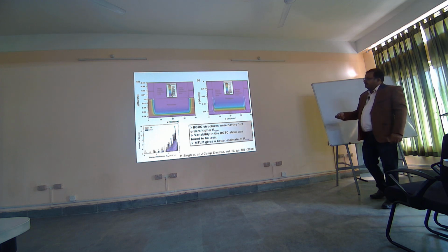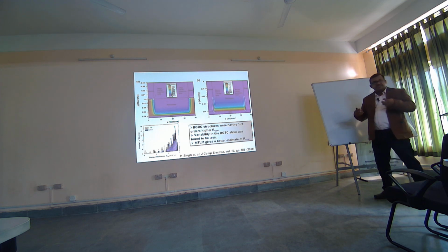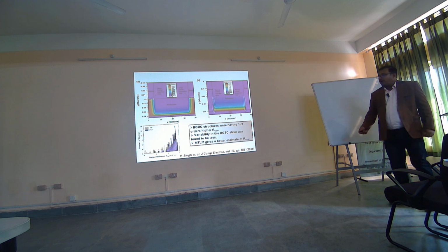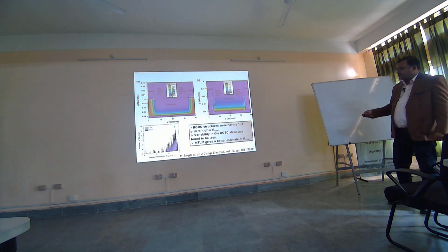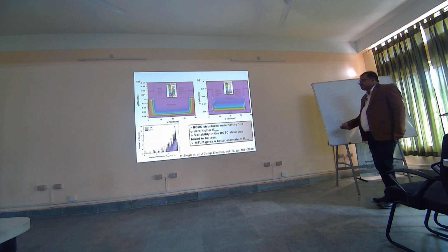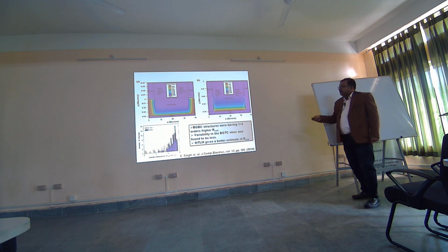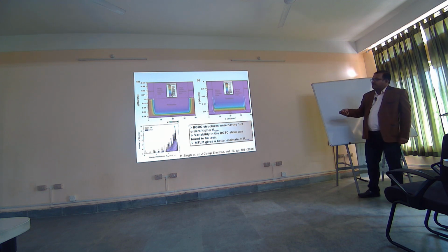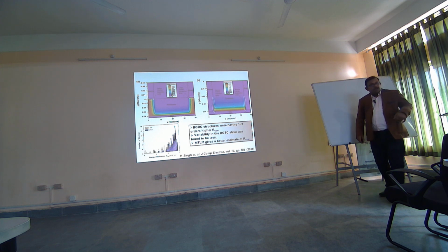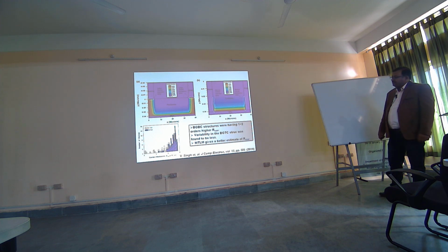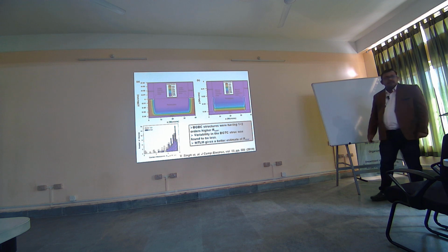Because of that, the contact resistance is also dependent on the interfacial area through which injection is happening. So we found that it is mainly because of the large interfacial area that the top contact structure offers that you have a much lower contact resistance in these kinds of devices compared to the bottom.